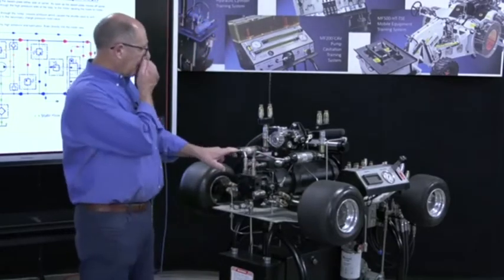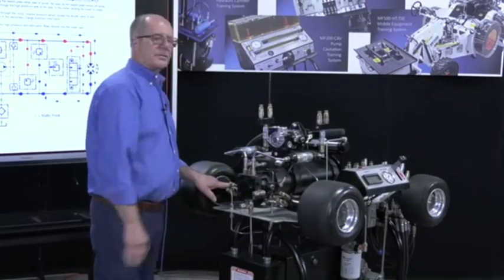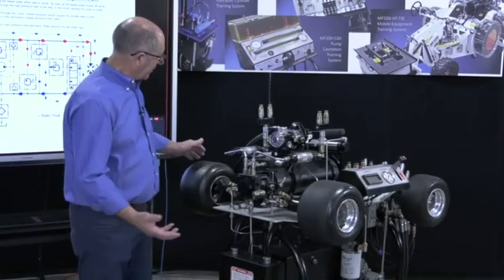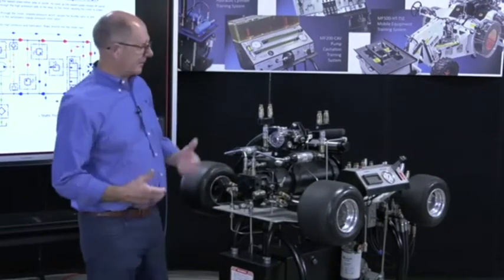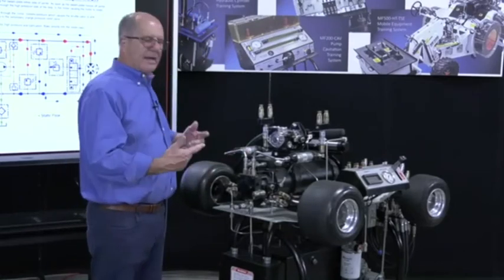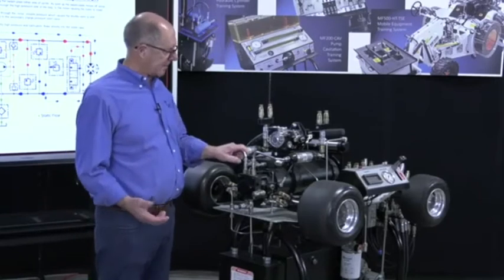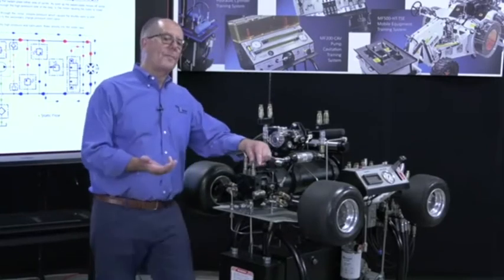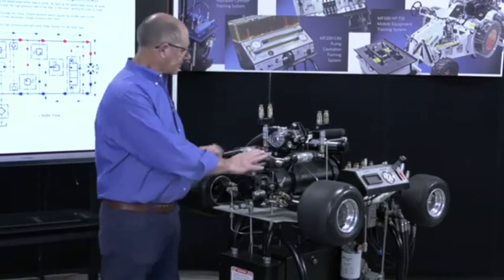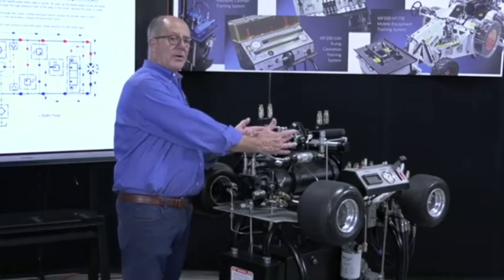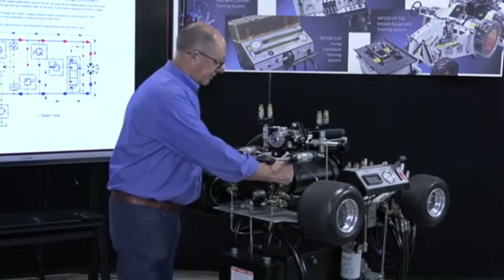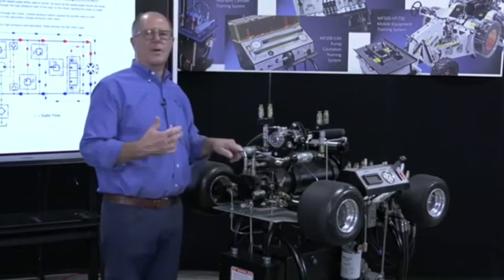We've also got dual high torque, low speed motors here. For safety, these things are not connected. We don't want one student to hold on to this and then another student, because students are adventurous, and then of course it wraps their coveralls up in it, and that's a problem. So they'll spin, but they're not connected to the shaft for safety purposes. We can connect this up in series or parallel so that you can demonstrate high speed and high torque. And because the main pressure relief valves are not adjustable here, we overrode them with another set of cross-port relief valves, which are adjustable so that the students can see what happens when they make adjustments on the valves.